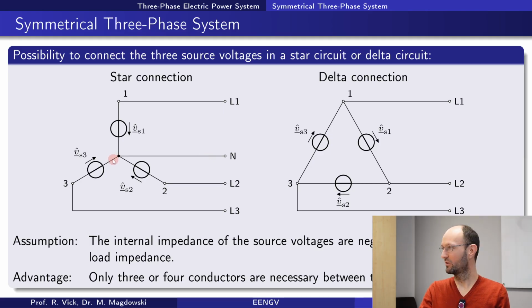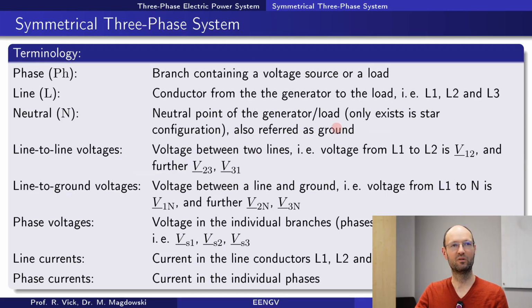Usually you don't want to have a current going over the earth. So a current over the earth always means that something failed in the circuit, because a fuse has blown, because a live wire touched the ground, touched the earth, something like this. So a current on an earth conductor should be only in case of failure, if something more or less terrible happened to your circuit. That's the difference between ground and earth. So ground, current on the ground, no problem. Current on the earth, typically a sign of a failure.